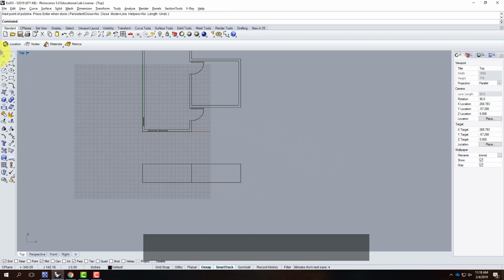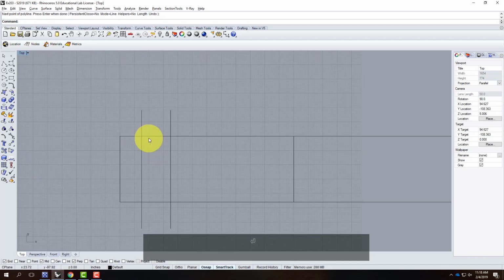So next thing would be those windows. I'm going to need those windows, so I'd come down here, and I'm just going to give myself a big line as kind of a guide of where this window is going to go. So we'll come down like that, and my window is going to fall on this wall right in here. Let's do a standard head height of 6'8". Let me trim those pieces off before I get started here.